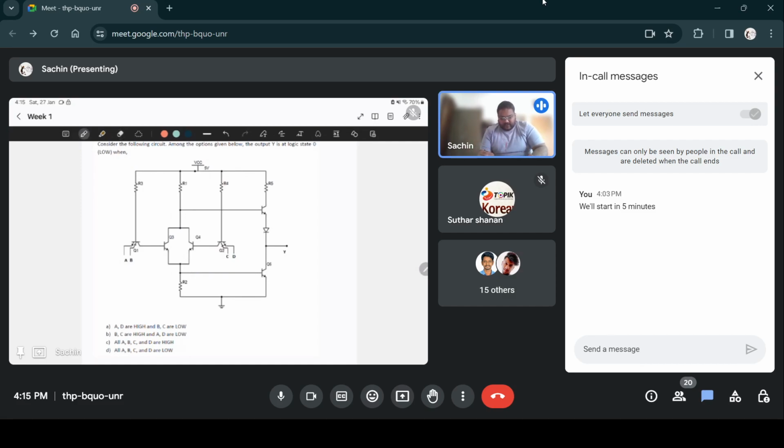What that means is that if it had only one of these branches, this would have been like a NAND gate, I think. So the output Y would be CD whole bar. And if you take only the part containing this A and B, then that would also be a NAND gate, which would give you AB bar. Since they are in parallel, this would be something like CD bar plus AB bar. I'm not sure if you understand what exactly I'm writing, but that's what is happening here.